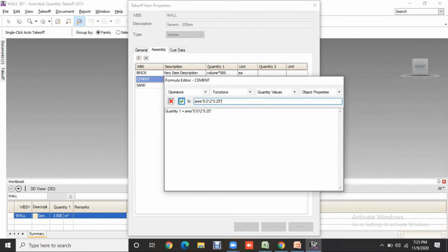After that, suppose you are using the cement, some part of the cement is wasted. We add an additional 15 percent. Suppose we are using 30% as the waste. It means we have to use 30% more cement, so it means 1.3. Suppose 30% will be wasted material, so you have to consider 1.3 in that case, right?